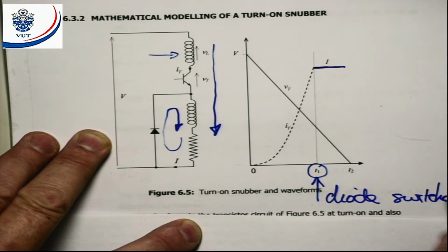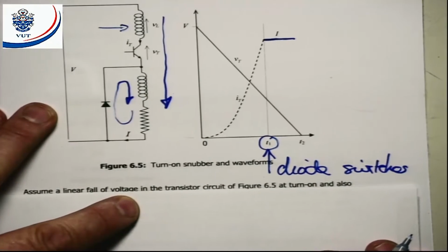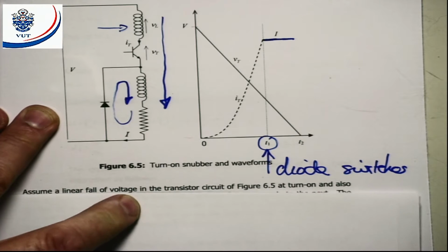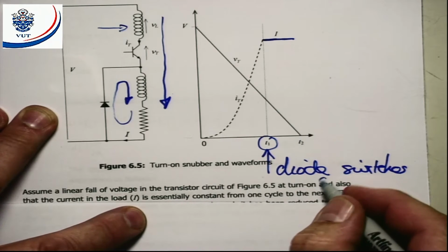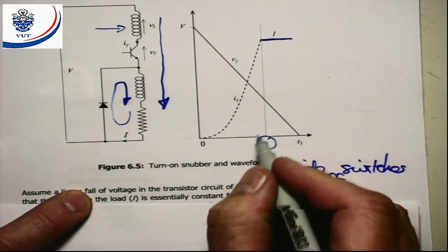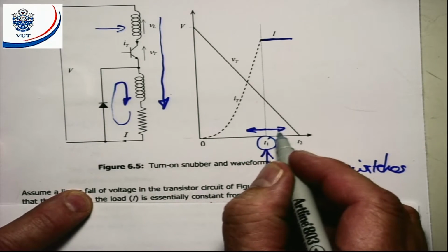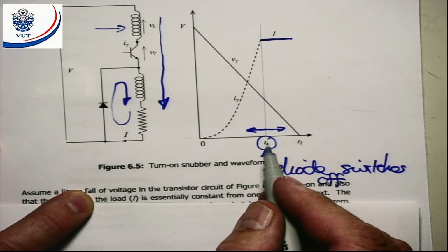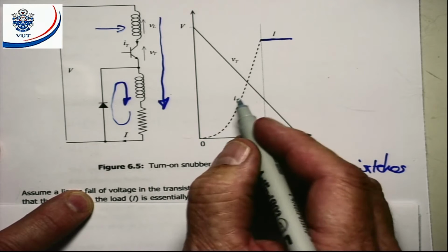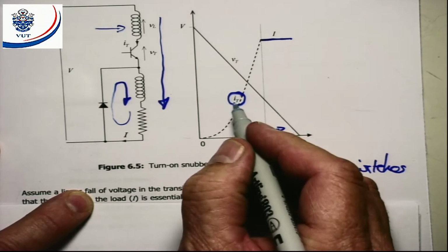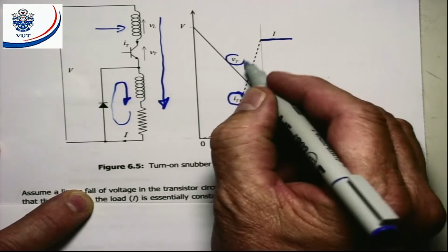What was it with the previous one? That was when T1 was when the diode switched on. Here is when the diode switches off. Once again, we now understand that we are going to determine the ratio from T1 to T2 for optimum, and instead of Vt, we need an equation for It, and we need an equation for Vt.